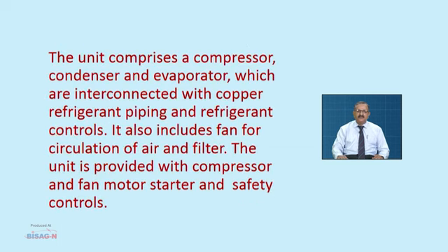The unit comprises a compressor, condenser and evaporator, which are interconnected with copper refrigerant piping and refrigerant controls. It also includes fan for circulation of air and filter. The unit is provided with compressor and fan motor starter and safety controls.